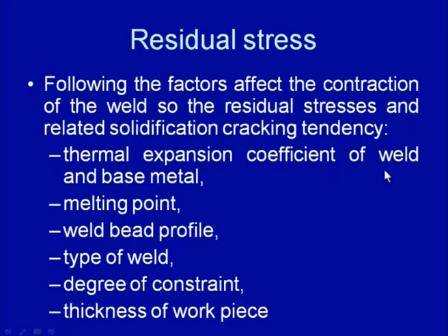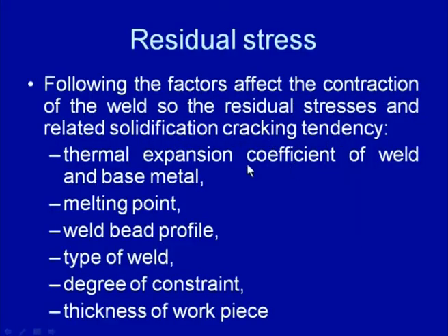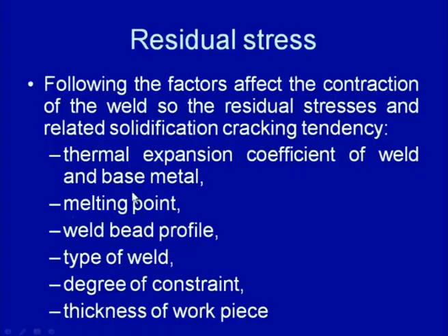One is the thermal expansion coefficient of the weld metal and base metal. In general, the higher the thermal expansion coefficient, the greater the residual stresses, and so the greater the solidification cracking tendency. Then the melting point: for aluminum alloys, consider the melting points of the filler metal and the base metal and their relative values. If the solidification of the weld metal takes place first, then the whole of the weld metal will solidify first.